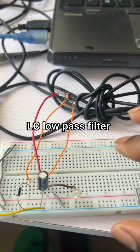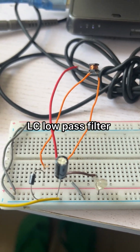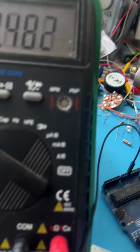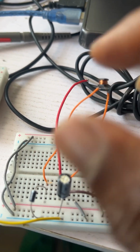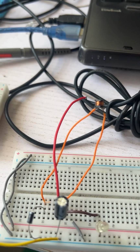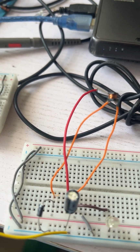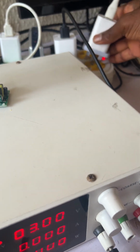And what is a low pass filter? It's just an inductor and a capacitor that you use to work on the average, such that I can have something like what is coming from this power supply. If you understand what a simple low pass filter is, then you can design a buck converter, a boost converter, a flyback converter. And my goal is to design a flyback converter. To make it simple, it means to design something like this, a charger. So let's continue.